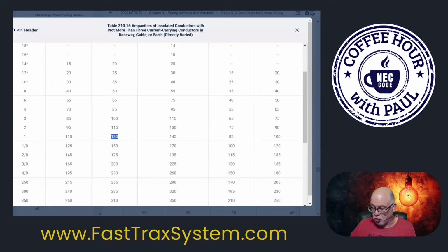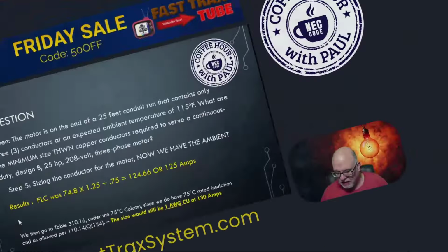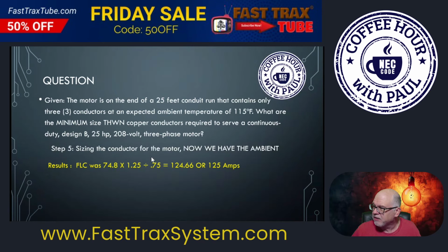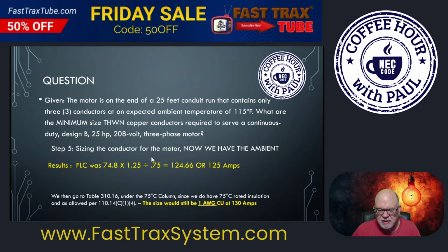So let's see what that is. Let's do the 130. Now I'm going to use multiplication because we're going down: times 0.75, and that equals 97.5. Well, 97.5 is perfectly fine, because if I take you back to the lesson, we see we needed a conductor that at least handled 93.5. So obviously 97.5 is good enough to handle it. So boom, boom, boom, that's it.